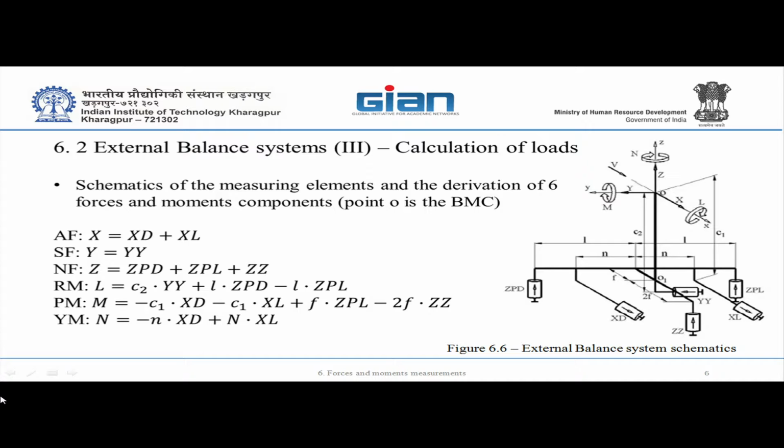Why? First of all, where are you taking your moments calculation? To which point? That place is called BMC, balance moment center. You have to define where your balance moment center is, because when you have to transfer your forces and moments from the balance coordinates to body coordinates, you have to know exactly where your balance moment center is.